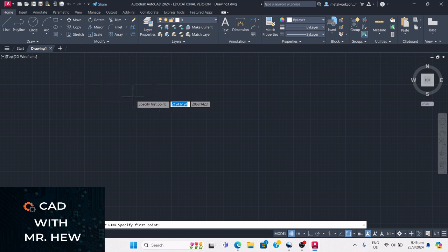You click the line, you come down here to turn on snap. The snap is just a function that enables the cursor to adhere to the grid, right? So if you set the grid, let me show you. If you set the grid, you type in the word grid, enter.